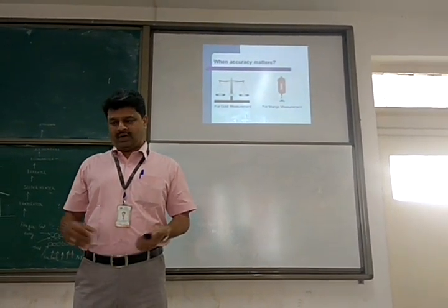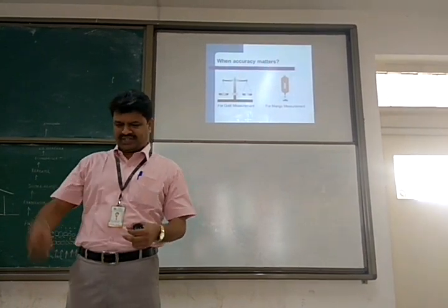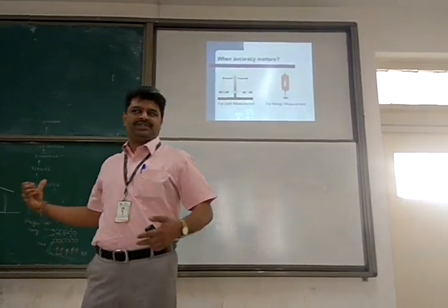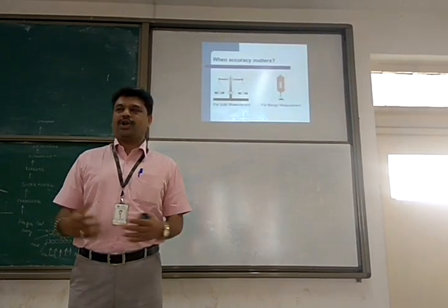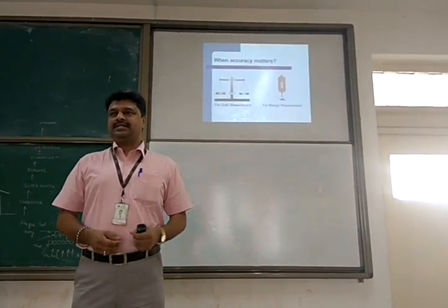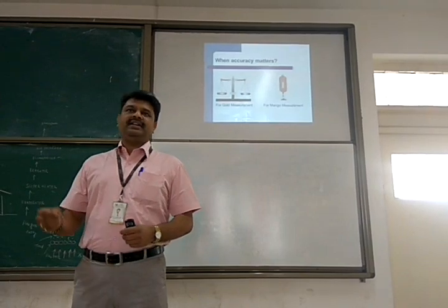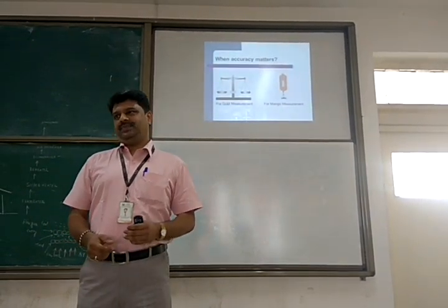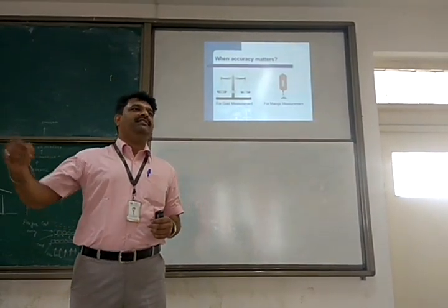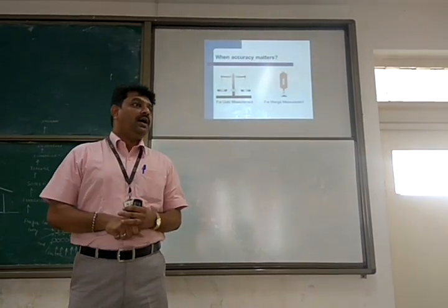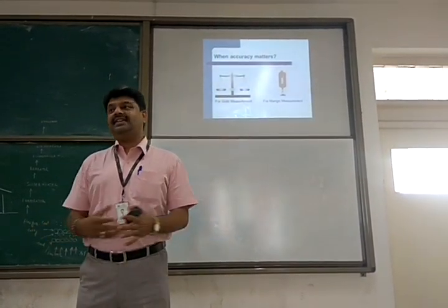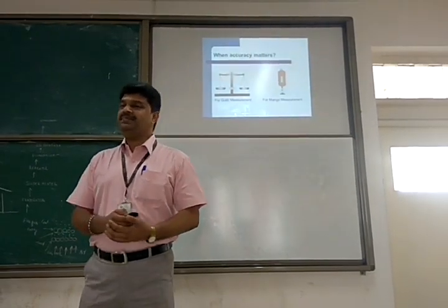You should not ask, okay, I'm going to measure temperature, so give me the best available in the world because I want to have the best instrument in my company. That should not be your idea. Because every small increase in accuracy that you demand is going to have a disproportionate increase in the price of the instrument.